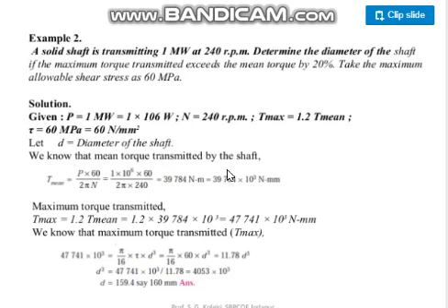That's why there is a meter there in watt. Therefore, what comes is Newton meter, and then Newton millimeter for converting it. You should put all values in millimeters, then only your answers will come correctly. Otherwise, you may be solving the problem correctly, but because of the confusion in the units, your answer will be wrong. Okay, so convert it into